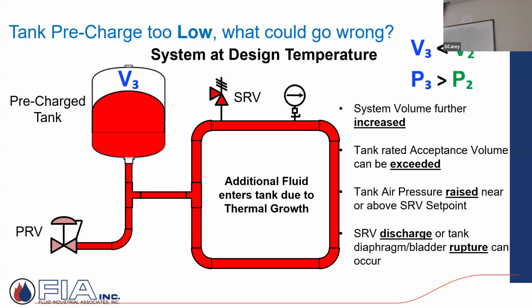So what we kind of subtly harp on in these slides is, as a specifying engineer, if you could throw it in the drawing, hey, this is going into this tall building. It's going to need this fill pressure. We know the mechanical room's down in the basement. Make sure you pre-charge your tank to whatever that number is, 35 pounds, 42 pounds, whatever. While it's not connected to the system, pre-charge it. Then some of those calls go away.